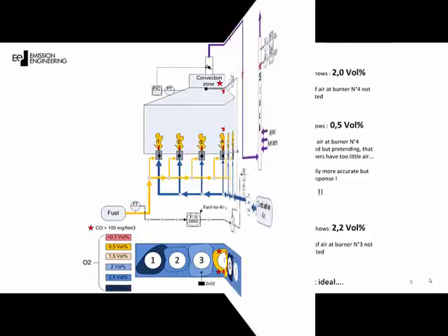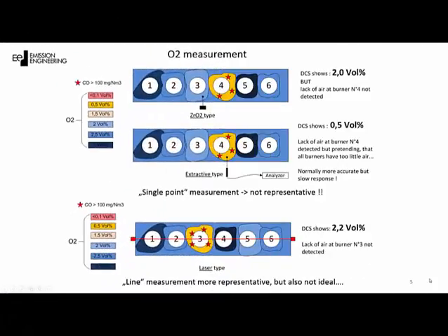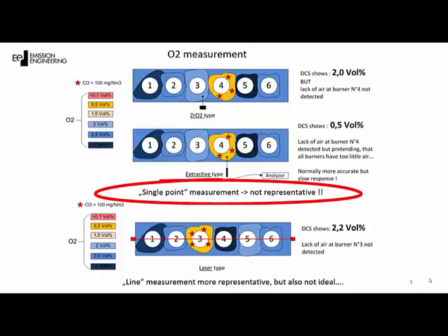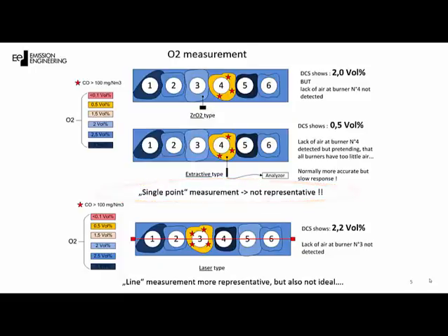Coming back to the way oxygen is measured, some refineries think they are able to resolve all problems with a different type of oxygen measurement device. Those mainly used are zirconium dioxide-based oxygen analyzers because they are more economical than those we will mention shortly. They provide single-point measurements, however, and the point that is measured may not be representative of the operation of all the burners.